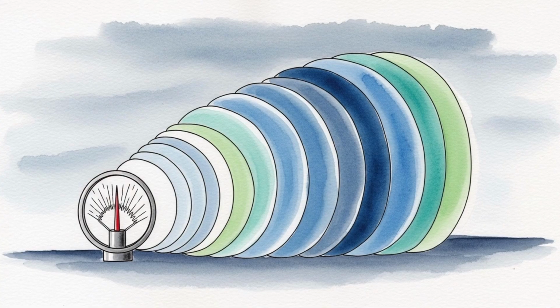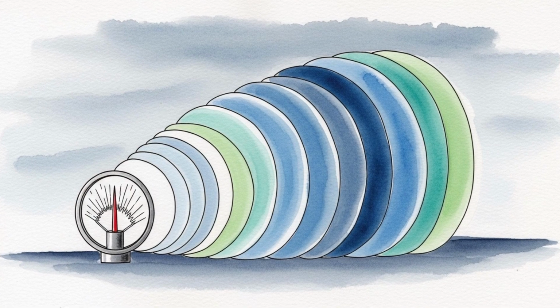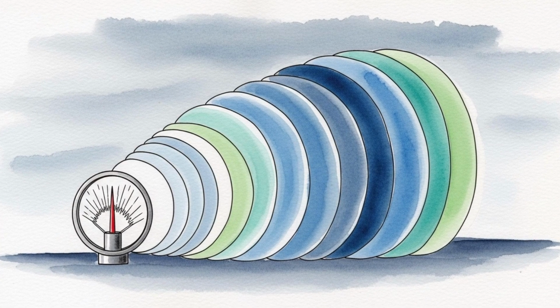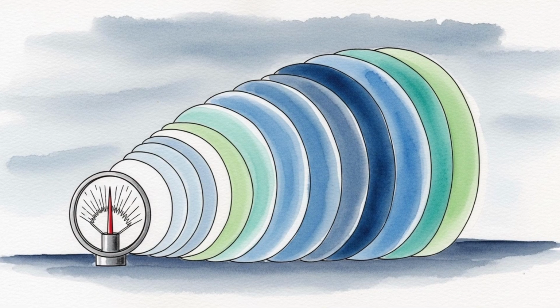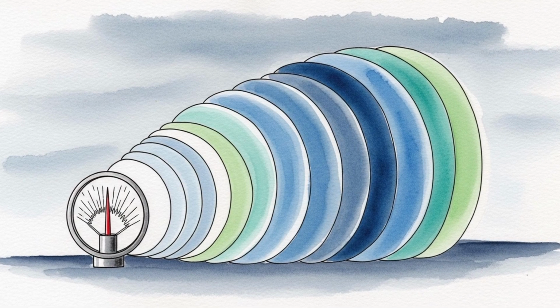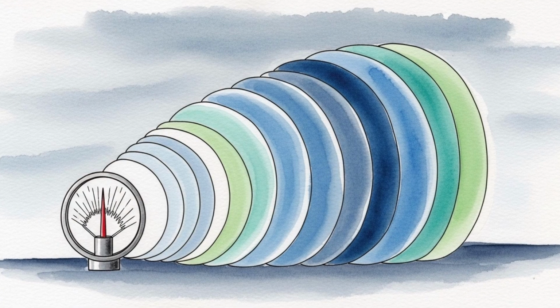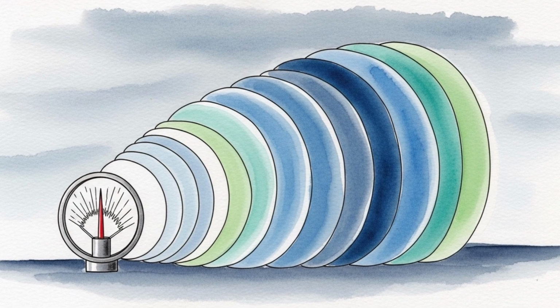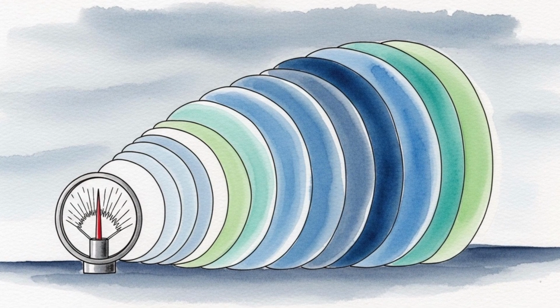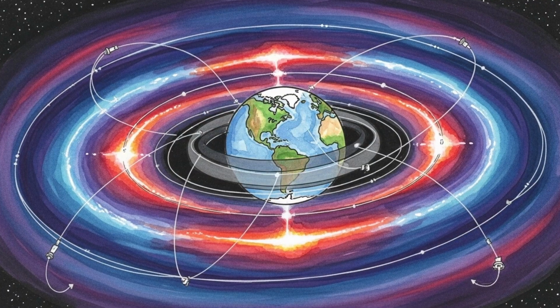Monitoring turns a diffuse hazard into specific numbers. Transformer neutral current monitors measure geomagnetically induced current directly. Substation recorders track harmonics, voltage, and reactive power. Phasor measurement units add high-rate visibility of angles and frequency.